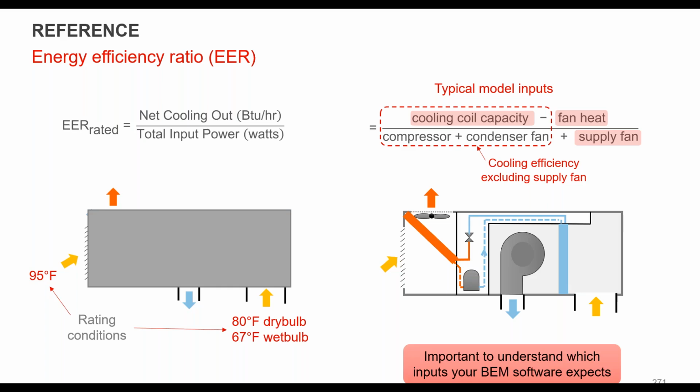So yeah, the other thing is to go to the manufacturer. When you get a selection sheet or a spec sheet from Daikin or Carrier, whoever it is, you would look and see, and they now are being better about reporting compressor power input for heating and cooling separately. So you'll see it for VRF for sure. They've been doing that for a while, but on the rooftops and this other packaged equipment, you'll now see the compressor and the condenser fans isolated.